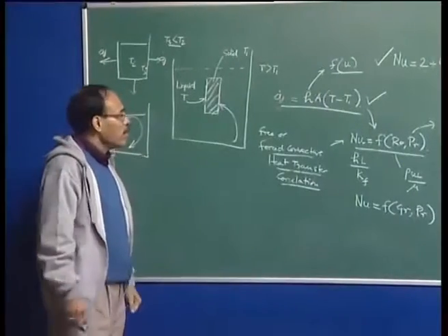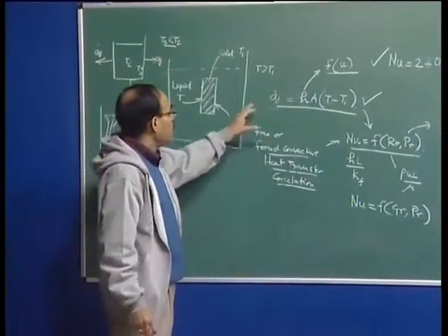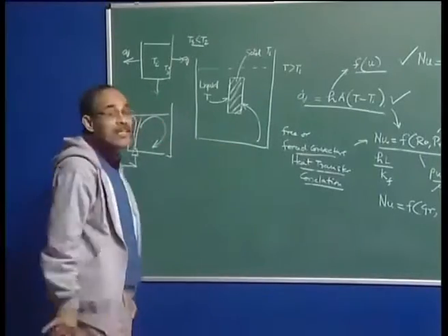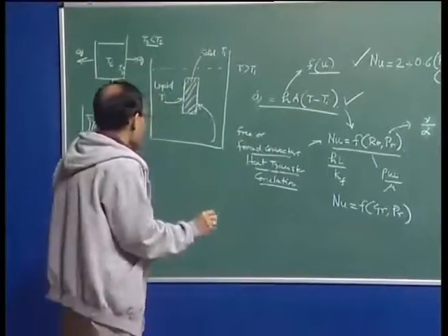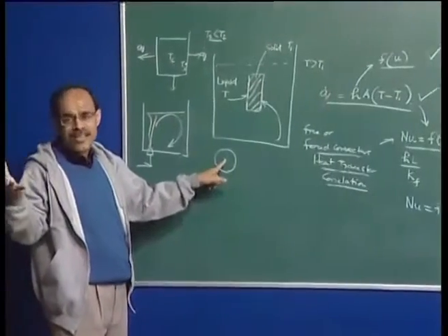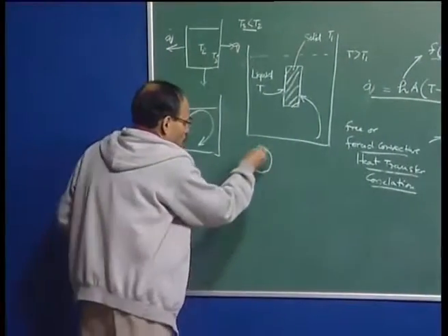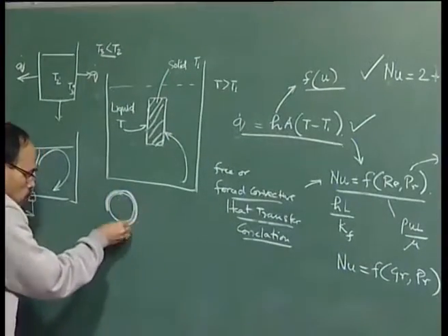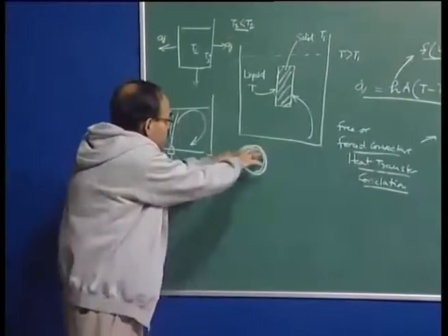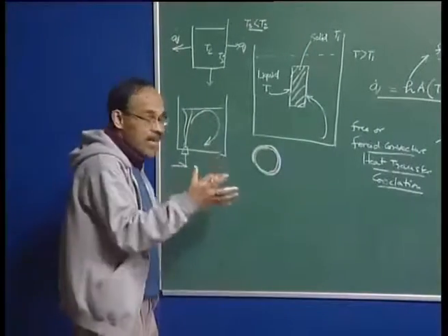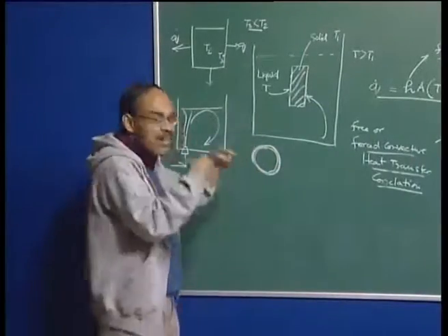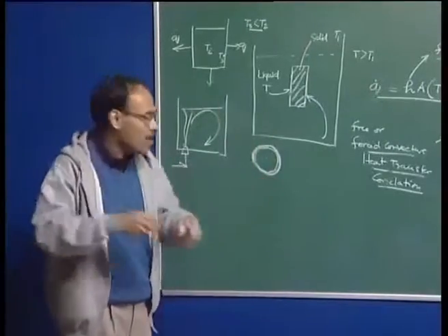Now, during melting, we must understand that solidification as well as melting is going to take place, particularly when you project a solid into liquid. For example, if you project this solid into a liquid, and this solid is at room temperature, a deoxidizer element or an alloying element, typically you form a solid crust. Now, this crust, when the material is submerged in the liquid, melts back. Initially there was no crust, so some solidification of crust takes place, then the crust melts back, and once the crust melts back, then the original solid is going to be exposed to the liquid. So, it goes like this.